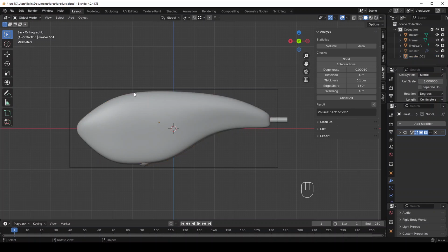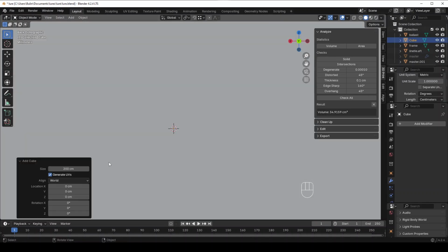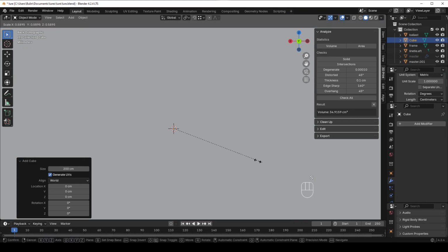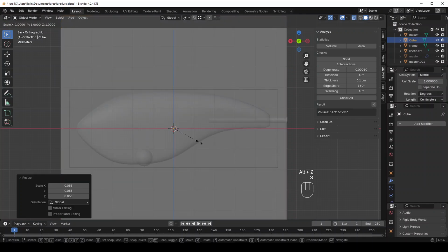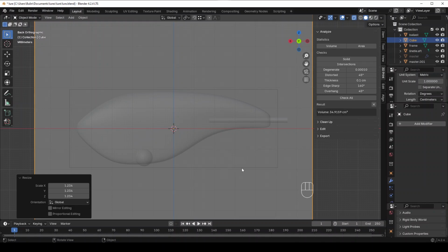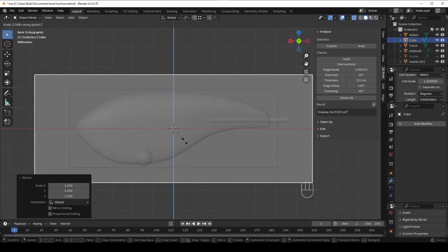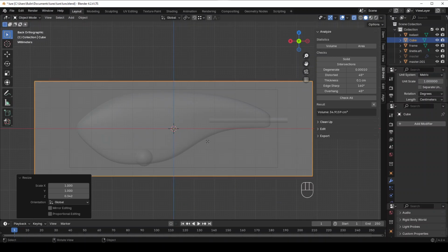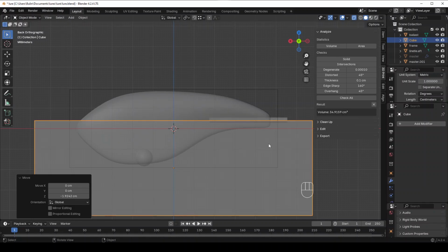So this part is going to get a little fancy, so bear with me. Click off of our master, hit Control A. We're going to add another cube. Again, it's huge. Hit S to scale. Bring it down where it's just a little bit bigger than our lure. Turn on our X-ray mode. Yeah, something like that. Along the Z axis, we're going to shrink it just along the Z. So S to scale. See, this doesn't need to be perfect. There's not an exact dimension. We're just getting something that we can cut our lure in half with temporarily. Again, I like to make this one wire.